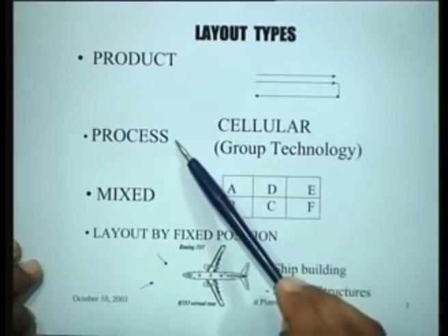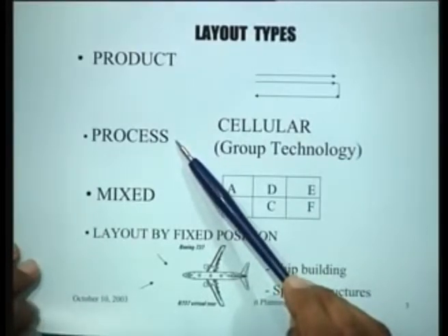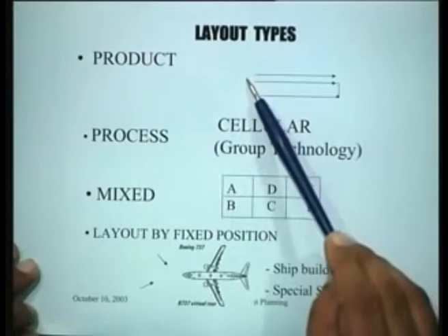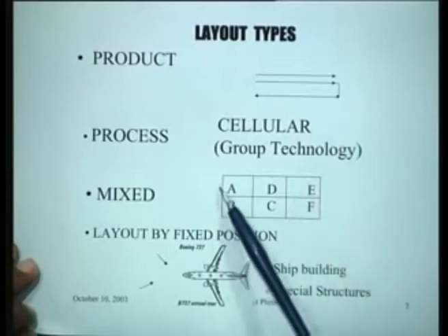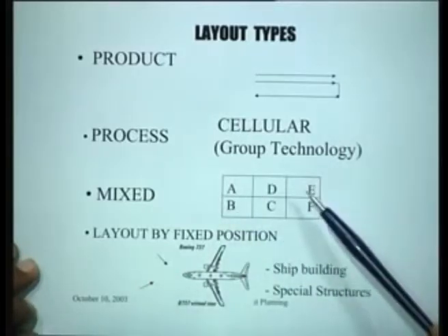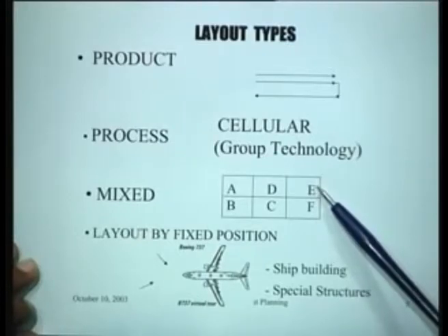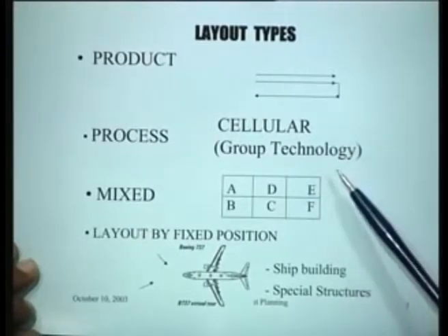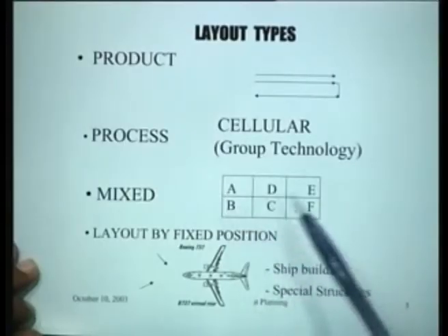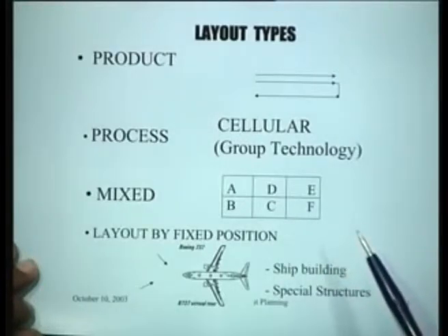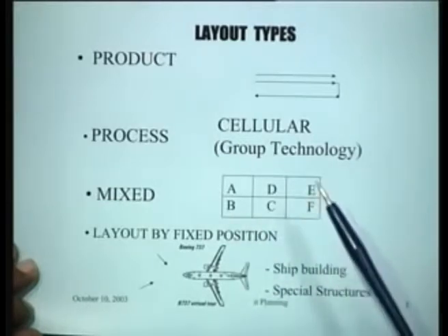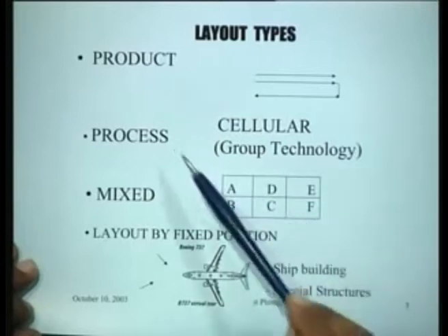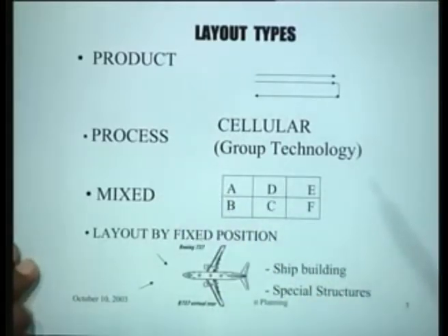So the major advantage of this type of layout is the product variety that it can handle, unlike the product layout which typically handles a single type of product. So you can make a variety of products in this particular layout, and of course, what will be the major problem here? The major problem will obviously be a large number of products moving here and there, so there will be a lot of confusion in terms of movement. There will be a lot of delays as products wait and move to different departments. Therefore, the production times generally tend to be large in such situations.